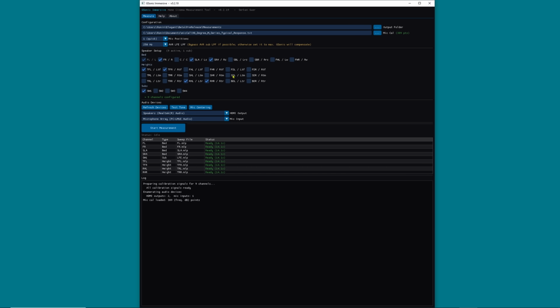Choose your number of mic positions: 1 for a quick check, 3 for the default, and up to 16 for a comprehensive spatial measurement of your room. Next, enter your AVR's low-pass filter, LPF or LFE setting, so the software can reverse its effect. Options include 200 Hz, 250 Hz, 320 Hz, or bypass. GSonic will save a 10 decibel boosted raw measurement of your subwoofer, as well as its reverse low-pass applied and volume-corrected version for the main listening position.